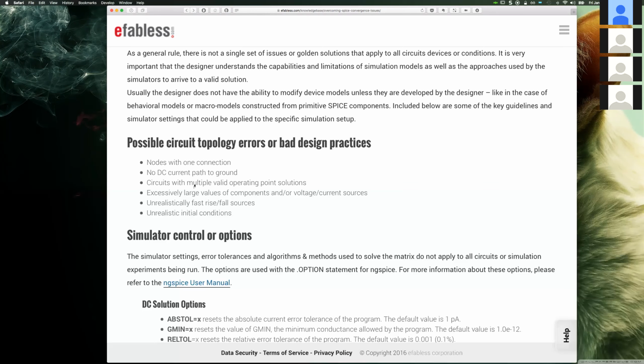Now, this is where the startup circuits come into place, and in general we are told that you know you're going to have these circuits that have multiple operating points. But there's not a bulletproof answer to identify these operating points unless you act on it and treat it with judgment, interrogating or identifying points in the circuit that have this property.